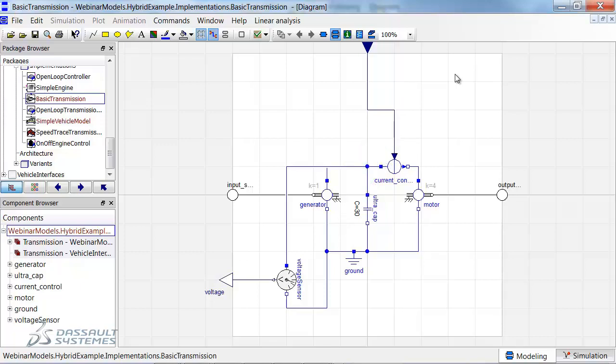The important point here is that we don't need to implement regenerative braking. We implement a mathematical model of each component and then impose conservation equations across all the connections. As a result, we are always assured an accurate accounting. This is important because if model developers had to implement all the consequences of the different modes for each component, it would be very easy to overlook something. With acausal modeling, all of this is taken care of.